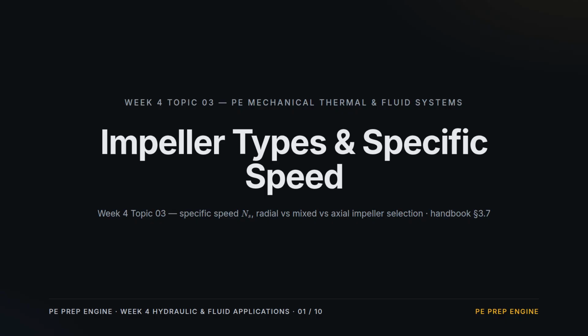Topic 3 of Week 4. Impeller types and specific speed. A short, low-yield topic, so we'll keep it tight. Specific speed bundles a pump's speed, flow, and head into one number that tells you which impeller geometry fits. Radial, mixed flow, or axial. It's a selection guide, not a performance prediction. And the unit's convention is the only real trap.